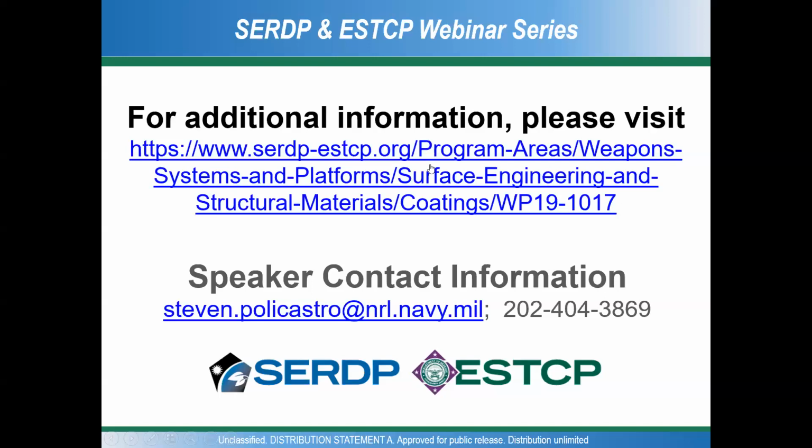Okay, great. Does the EIS modeling show decreased resistance with time? And then does that suggest electrolyte penetration? Yes. So over time, that pore resistance is decreasing the longer it's exposed to these environmental conditions. That's why we're using that as a proxy for the coating degradation. At some point, the inhibitor is leaching out, and we're not seeing that in the EIS data. That may be occurring at a level below what we can resolve, but we're using the pore resistance decrease as a proxy for the coating system degrading. Okay, got it. Thank you.